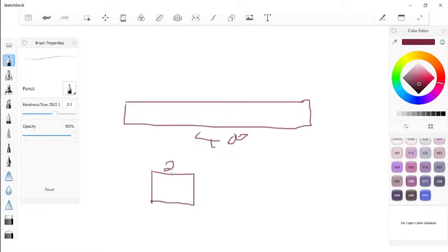So the breadth is 20 and the height is that, and this is a concentrated load or point load acting on this. If it's a point load, it will be acting at the center of this beam, and let's assume it is 20 kilonewton, and this is a simply supported beam which is supported at both ends.